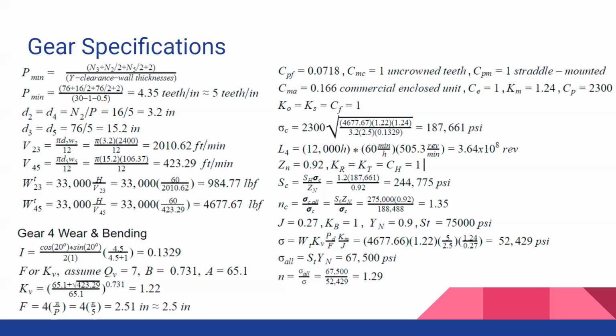The bending stress we found to be 52 KSI. The allowable stress we found to be 67.5 KSI. And using those, we found a safety factor of 1.29.